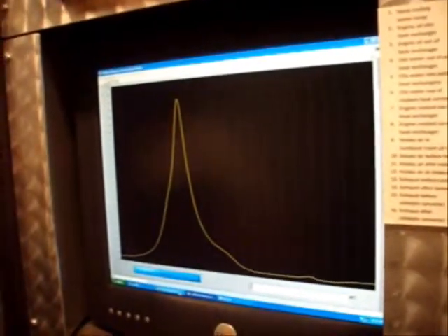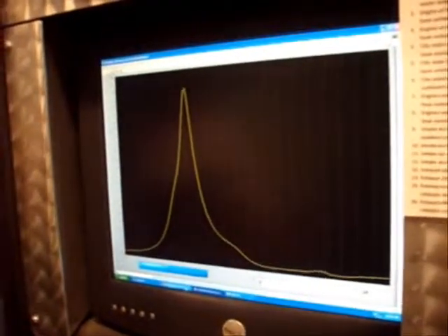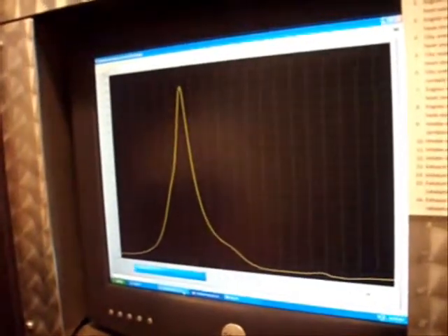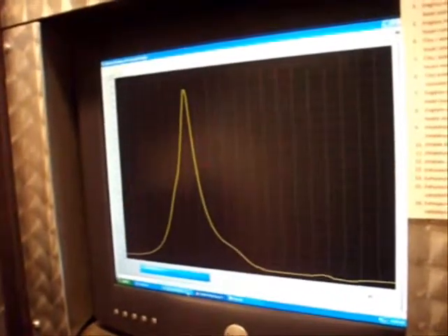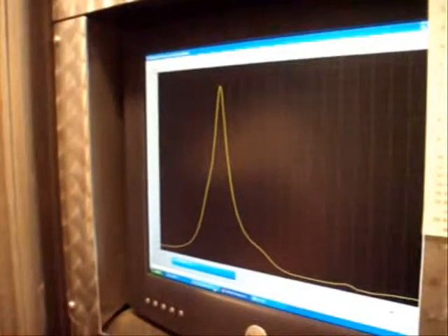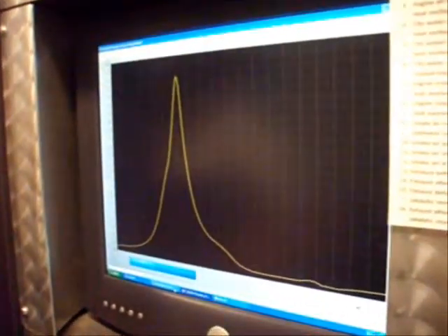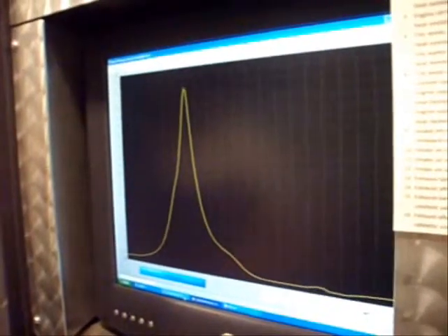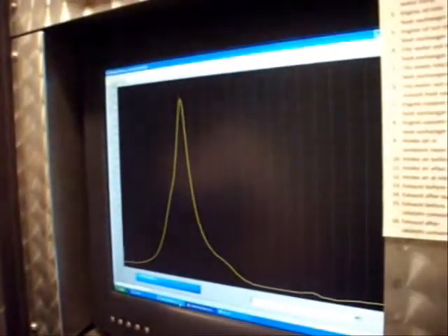So as the combustion process occurs, it does work on the piston by pushing it down, thereby increasing the volume of the chamber. So using our pressure trace that's fed by our cylinder pressure transducer, we're able to look at the cylinder pressure in real time throughout the entire 4-stroke Otto cycle.